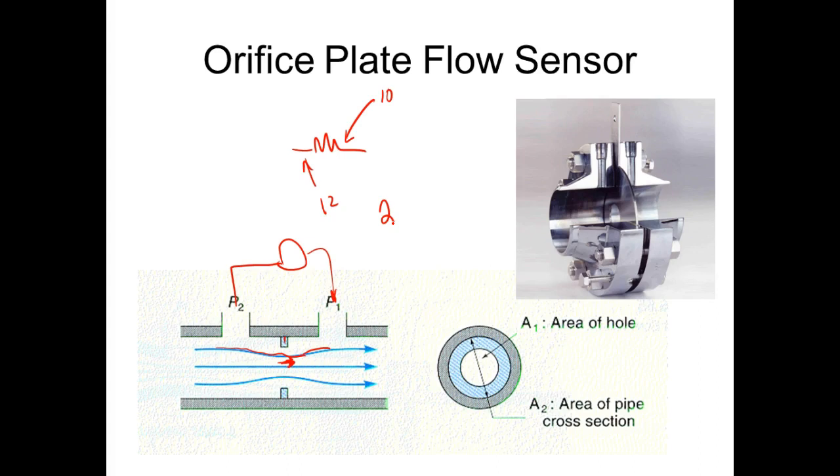Exactly the same way. So what we're doing is we're sending the flow through a precise resistance opposition. We have a pressure drop. We measure that pressure drop, and then the instruments use that to calculate the flow. They're very, very popular. This impedes it a little bit, right? Gases work pretty good on this, but in liquids, these guys will have a tendency to create what we call eddy currents over here when it comes around.